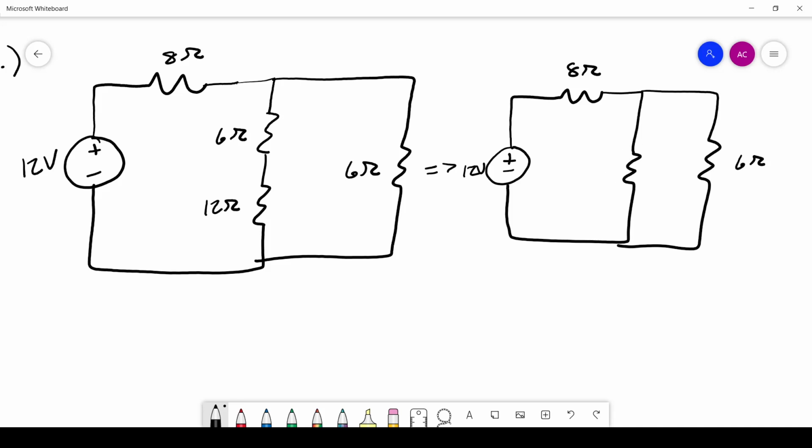All right, so now what is the value of this resistance right here? Well, we're taking 2 resistors in series, so that means we're going to add up their resistances. Skip the math just to keep it concise. It's 18 ohms. Okay? So that's one step that we've taken. Next step. Is there anything you can see that needs to be done? Hopefully you're shouting at your screen right now. There's 2 resistors in parallel. We know how to simplify those.